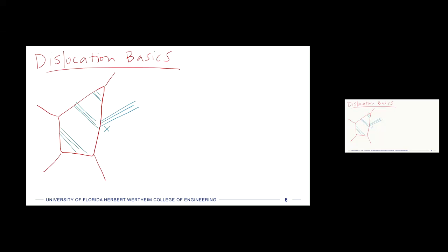So it's hard to change directions. And the second reason why they don't really go through grain boundaries as easily is that the grain boundaries are where there's more opportunity for impurities, other defects, toughening agents, et cetera. And so cracks don't necessarily propagate along grain boundaries. Sorry, not cracks, dislocation bands. We're not at a crack just yet.